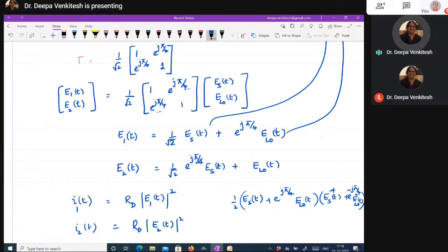If they happen to be balanced detectors, then if there is any common mode DC current that is generated, for instance, if my output has a DC current, and it is fed to a balanced detector instead of a regular detector, you have a chance of cancelling out the common mode DC current, and you can retain only the AC part of it, right? So that's where you can also understand the importance of a balanced detector.